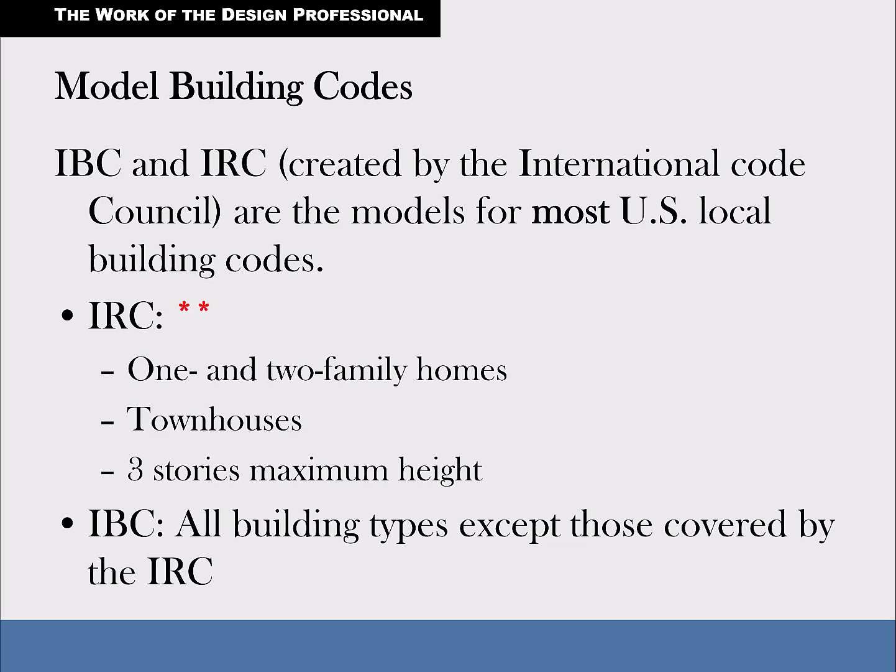Or townhouses. Well, that sounds strange. Hey, that's a bunch of buildings together. Why would that count? Yeah, only when they really are truly townhouses, when they're side by side. The whole thing is about egress, safety, life safety in an emergency, getting out of the building quickly. And so you can have them touching each other on the sides with a firewall system that's going to be specified in the code. But you got to be able to get out through the front and the back of that building. Oh, and if your house is more than 3 full stories in height, then you have to use the IBC, the regular building code, the International Building Code.